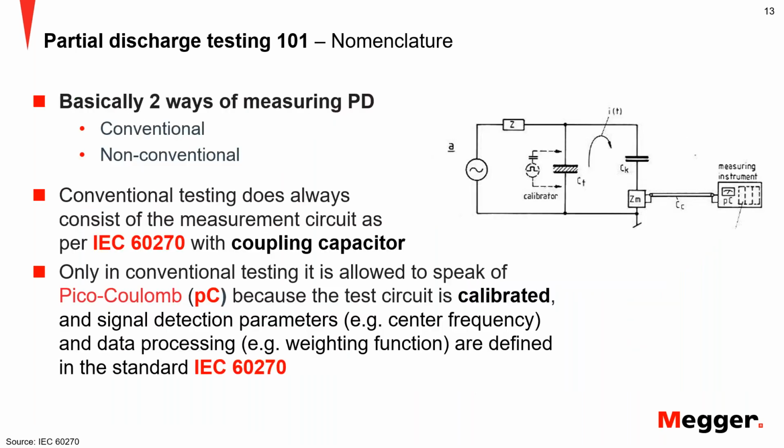Now, in terms of testing and standards, this is why we do not want to go into the scientific part of PD testing. There's an international standard that is very substantial, very deep, very broad. It's IEC 60270. It's pretty much the international go-to standard for PD testing, basics, explanations, test circuits, mathematical calculations of the different things the software is doing today. So, and again, very easy.